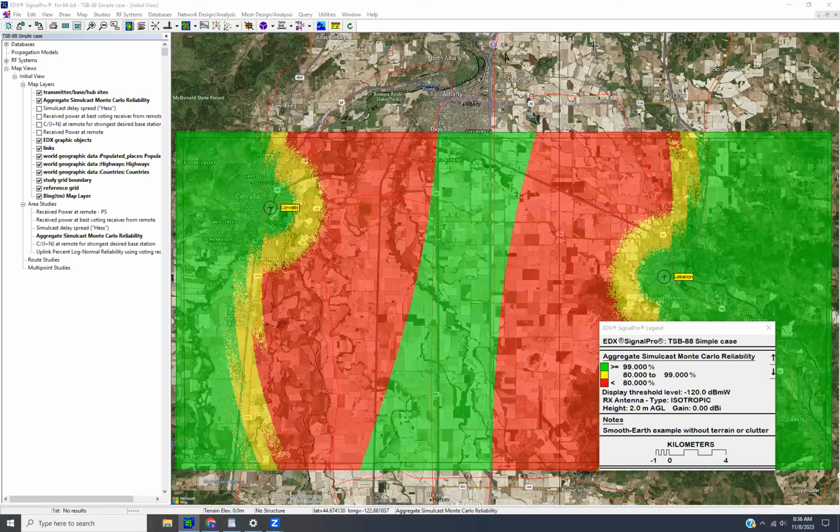Now, that will do it, and really these transmit parameters on the site won't matter at all. I have seen people be sort of worried about that and take their ERP down to some arbitrarily tiny amount of power, but that works as well. Effectively, you'll see no coverage from that receive-only site. But really the right way to do it is to use your transmitter groups. And if you've got some sites that are receive only, just make a transmitter group that has your TX sites versus your RX sites, and be sure to point to those groups in the study like that.